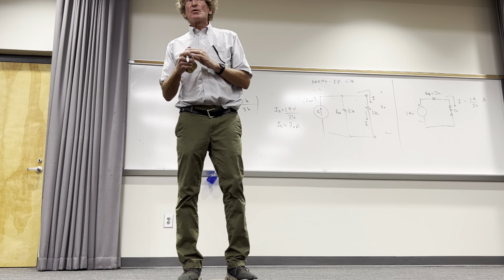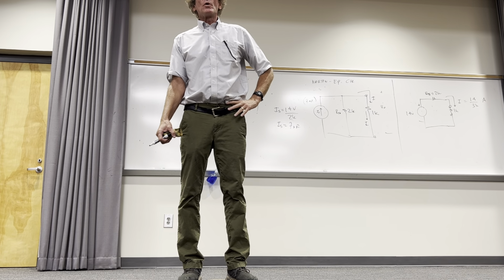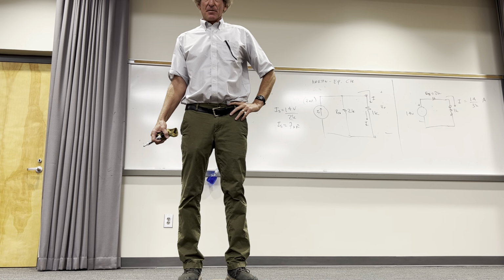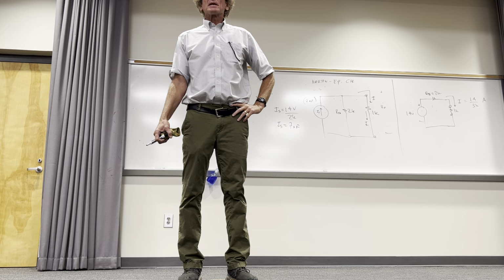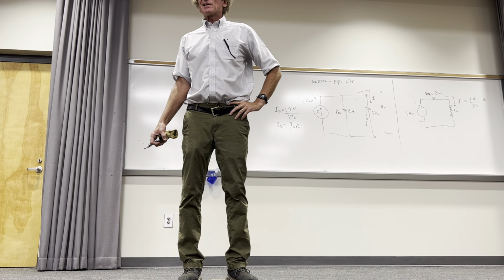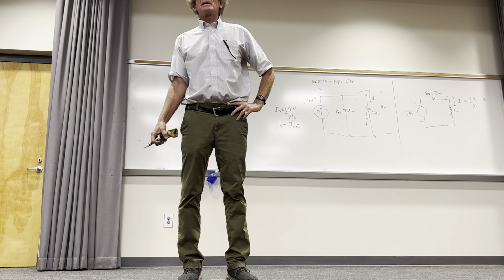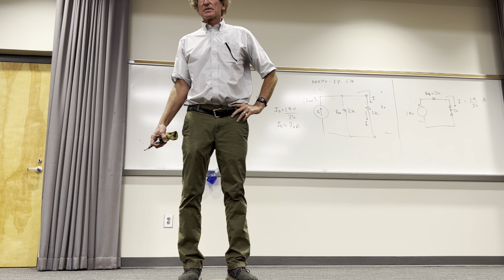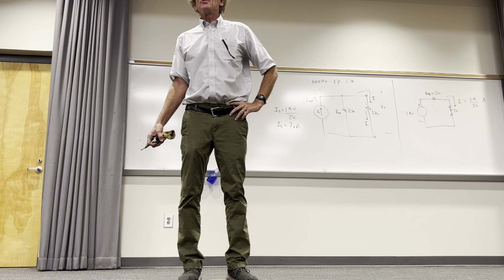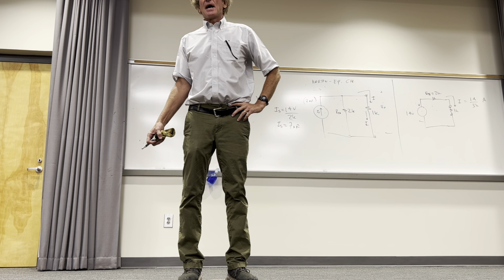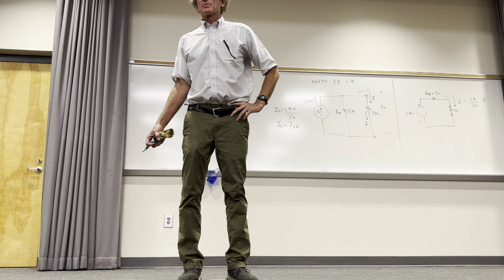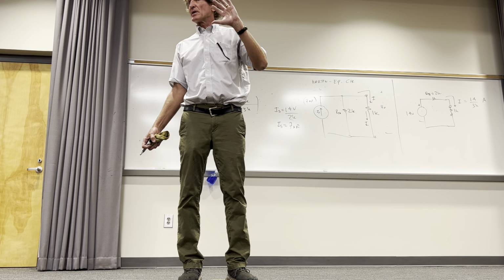These are Thevenin-Norton, write that down, Thevenin-Norton equivalent circuits. And in the book, he's going to be talking about them. Now, there's one thing I didn't cover yet, and I'm not going to cover it quite yet, and it's called finding the Thevenin equivalent circuit when you have dependent sources. In that case, the open circuit voltage is still the same, but to calculate R Thevenin, you literally have to put a voltage on the terminals where you remove the resistor and find the equivalent current caused by that from the actual voltage source that you put on. This is a little bit down the road. I'm not going to cover it right now.